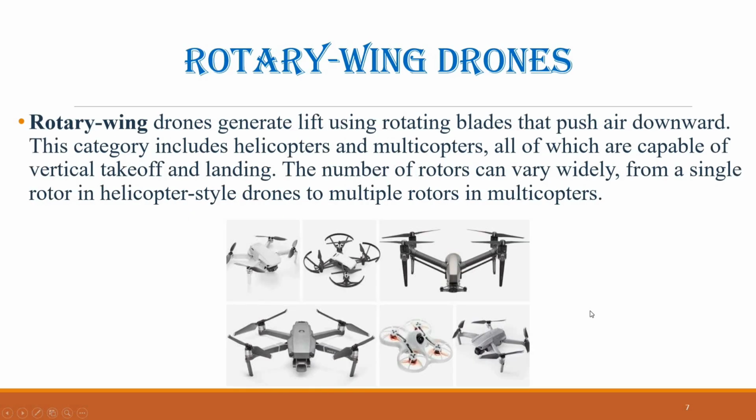Rotary wing drones. Rotary wing drones generate lift using rotating blades that push air downward. This category includes helicopters and multicopters, all of which are capable of vertical takeoff and landing. The number of rotors can vary widely, from a single rotor in helicopter style drones to multiple rotors in multicopters. These drones are especially popular due to their ability to hover in place, making them extremely versatile for tasks such as aerial photography, inspections, and surveillance.